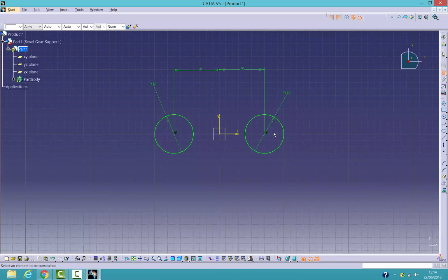If I was to just say do from point to point, it wouldn't turn green because we have to say it's 70 away from the origin here and 70 away here, adding up to 140 obviously. If it doesn't turn green by doing this, you didn't follow the blue checkered line, you just did the circle. So what you have to do then is add another constraint. So you're saying that the center point of the circle and the height between the horizontal is 0.